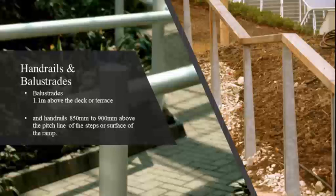It is important to guard with a balustrade or handrail where the total rise of the steps is more than 600 mm, or there is a drop of more than 600 mm at the side of a ramp, flight of steps, or balcony. The handrail height on steps and ramps should be 900 mm, measured vertically from the nosing of the steps or surface of the ramp. The rail should be 40 to 50 mm wide for easy hand grip.